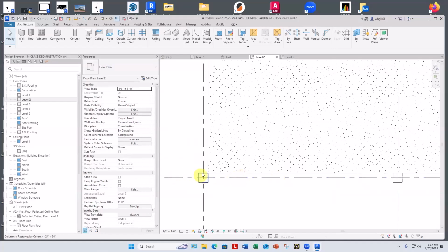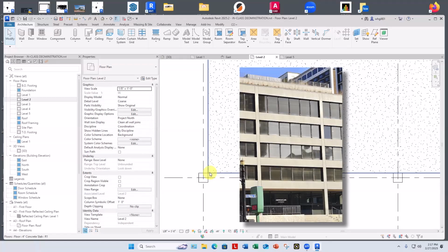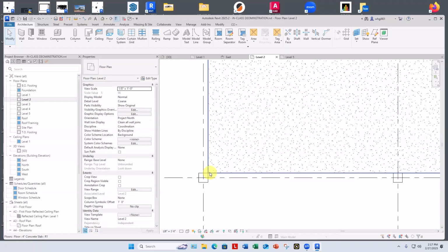I had you before running the wall all the way across. The problem is that it just visually smeared the wall and the columns together, and they're not. The columns, you can see them going all the way up as separate pieces, and the walls butt into them. And I want to be able to express that. So part of that was, remember when we edited the family of the column, we said don't join with things. So this will understand these are separate entities right now.